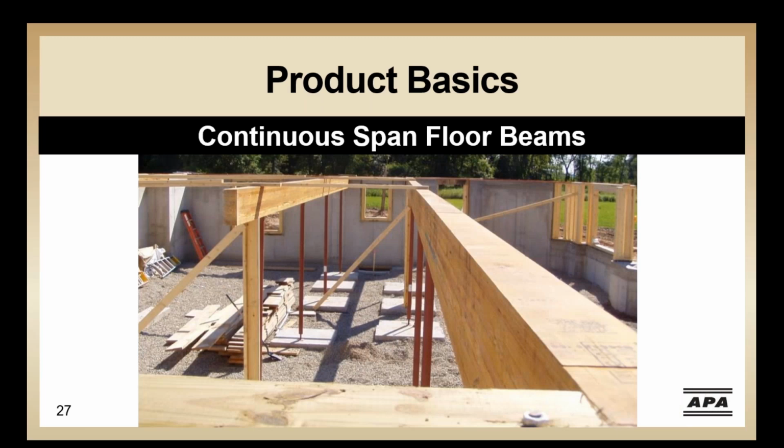In basements or crawl spaces, beams can be either dropped or installed flush with the joist framing and left exposed. In basements, drop beams allow for an easier installation of the floor joists, especially if I-joists are used, which can be installed on a multi-span application over the beam. In addition, these beams, being available in long lengths and multiple widths and depths, can be used to improve the floor performance compared with dimension lumber beams, which would be limited to shorter spans, although they need to be spliced. Structural composite lumber and stock glulam beams are both suitable for basement or crawl space applications. In finished rooms, SCL and stock glulam beams would be acceptable if concealed, or an improved appearance grade glulam may be used if the beauty of the exposed wood is desired by the homeowner.